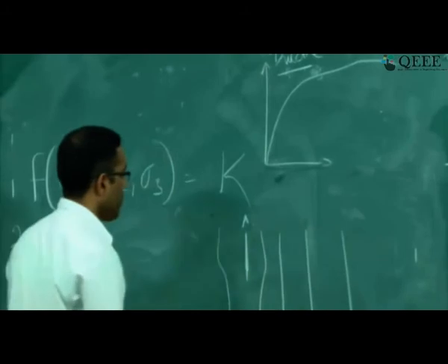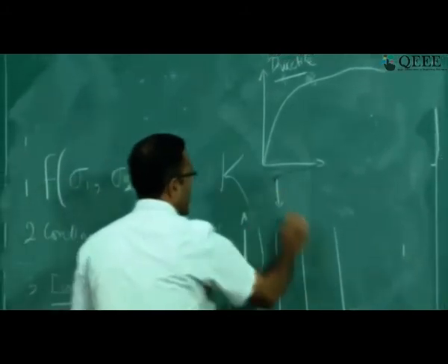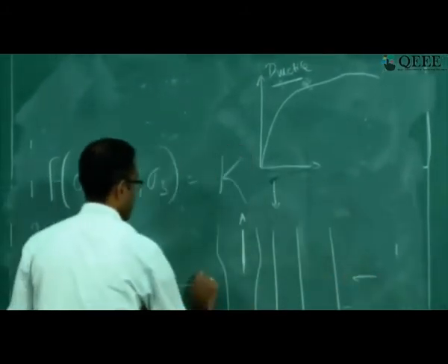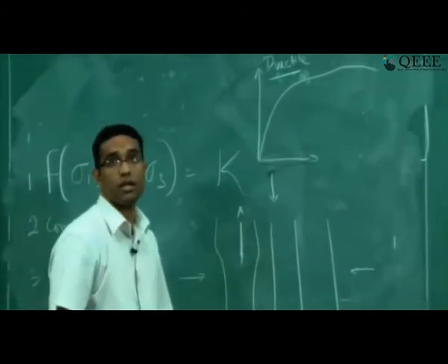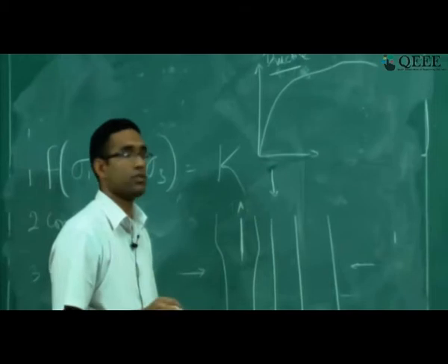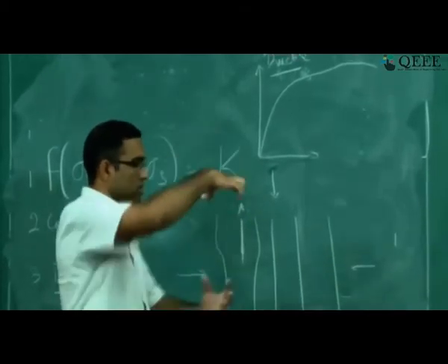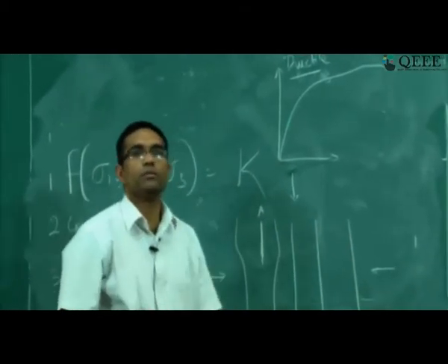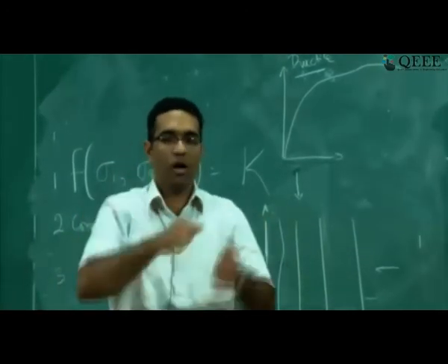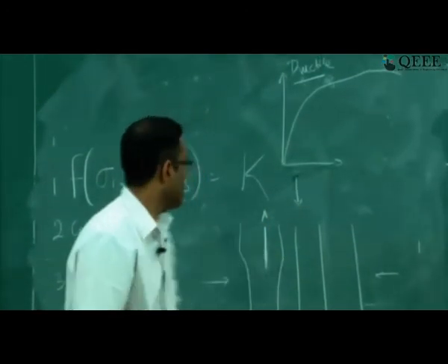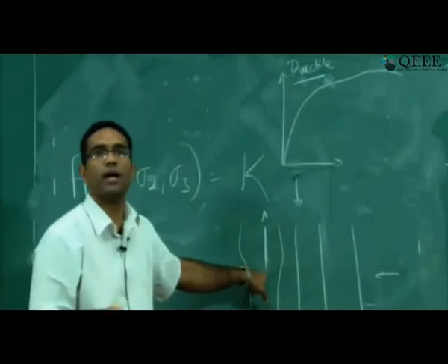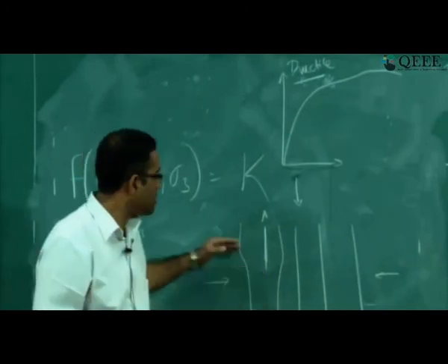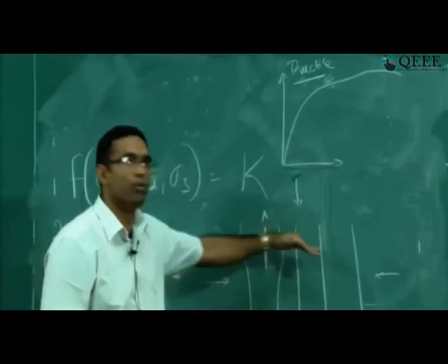Okay. Suppose I am taking this crystal structure and exposing it to hydrostatic stresses. That means from all the three directions it is being equally stressed, either pulled or pushed equally. It will not cause this dislocation to move, isn't it? It will just stay there. You need some sort of imbalance for the dislocation to move.